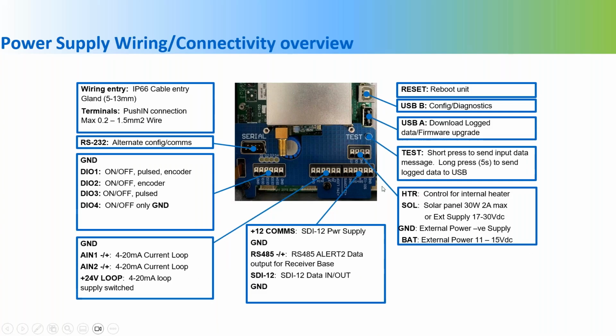If you zoom in on the left side where they have the I/O, here's the 4 points for digital or pulsed inputs, and they're not screw terminals, they're push terminals. If they have the mil-spec, it would be pre-wired for you. If not, you would have just a regular electrical connection to where you could pull your own cables and terminate.